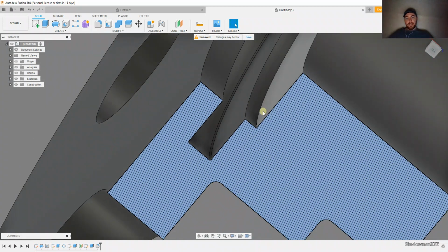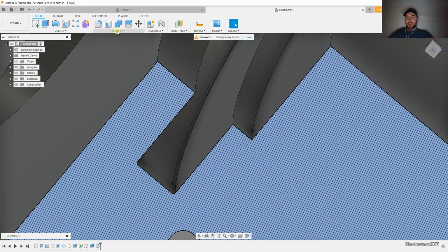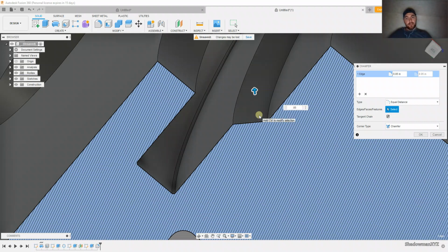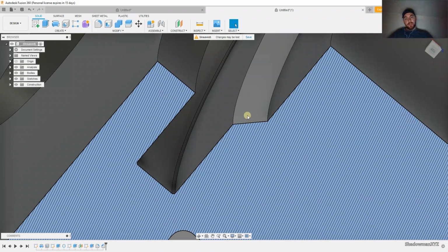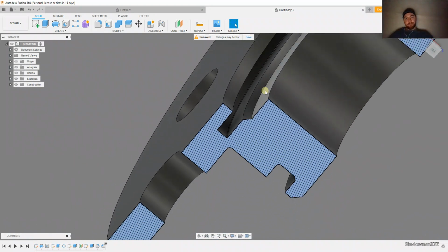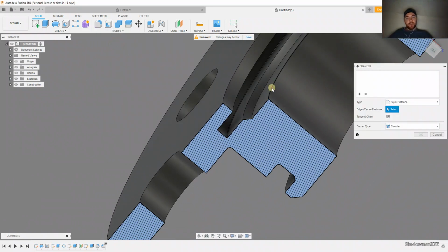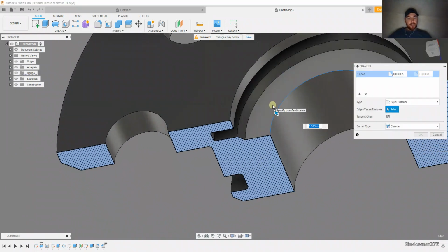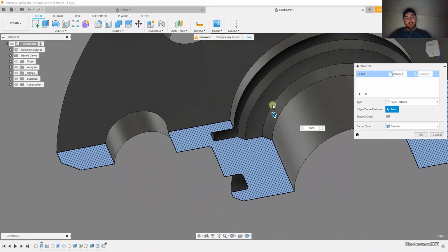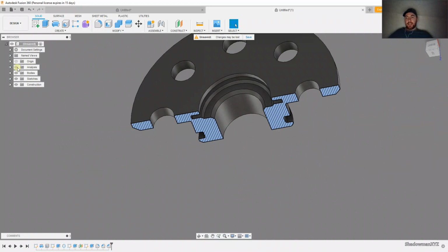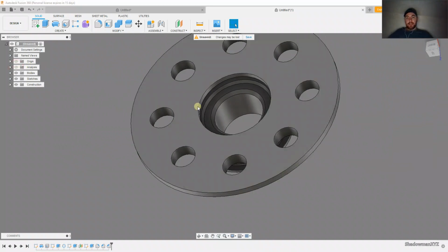Okay, say we want a chamfer right there. Modify chamfer, go like 0.05. Looky there. Put a chamfer here, modify chamfer, 0.0625. Let's do 1/16. Okay, let's turn off that analysis. Let's see what we've done.